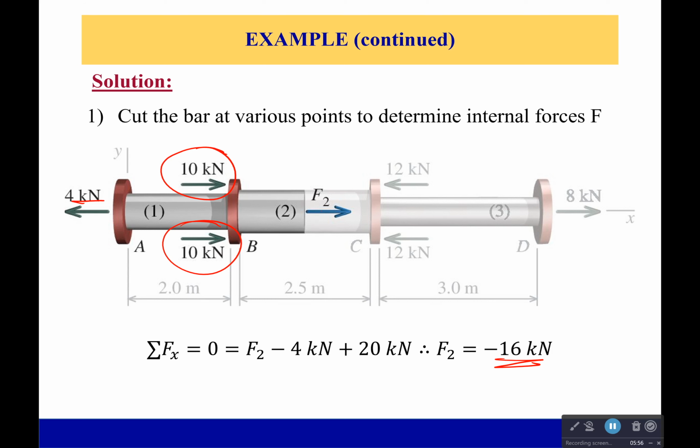Which means we honestly have force 2 pointing the wrong direction. That's okay. We'll just leave it as is right now because it would be compressive. We always draw our lines in tension because for our equation, compression is negative. So we'll leave it as a negative number.